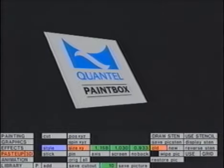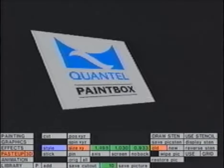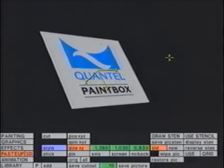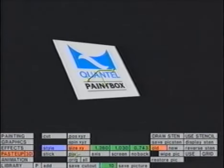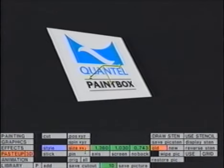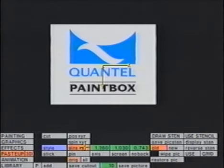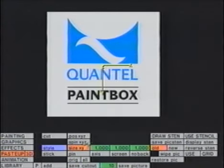Individual X or Y axis changes can be made following the same principles as for position and spin. At any point, we can originate position, or spin, or size. Or original all will do all in a single operation. By default, the axis will be positioned at the center of a cutout.